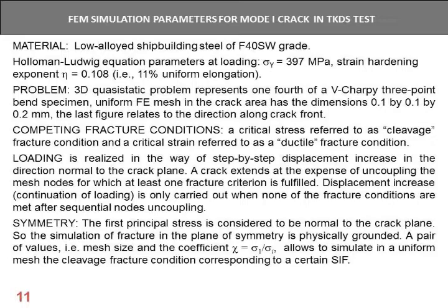A critical stress referred to as cleavage fracture condition and a critical strain referred to as ductile fracture condition are applied. Loading is realized in the way of step-by-step displacement increase in direction normal to the crack plane. A crack extends at the expense of uncoupling the mesh nodes for which at least one fracture criterion is fulfilled.